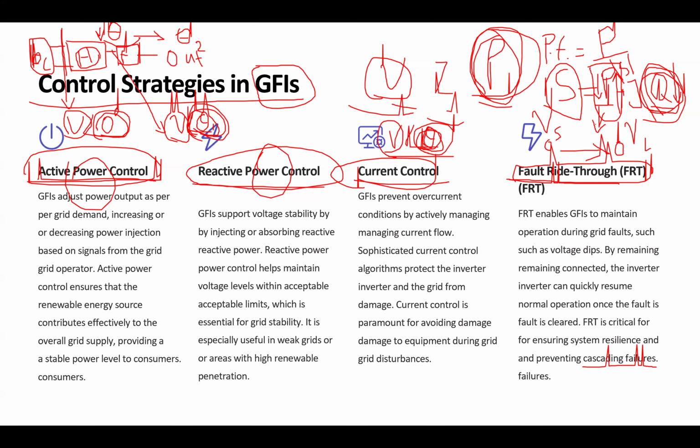So if you have a huge reactive consumption, that means your terminal voltage would fall down. Same goes if you have a huge reactive power injection, it would go up. So the grid has to answer that rush by injecting a lot of reactive power in a huge industrial scale. Motors normally have a capacity. Actually, mid level motors also have that too.